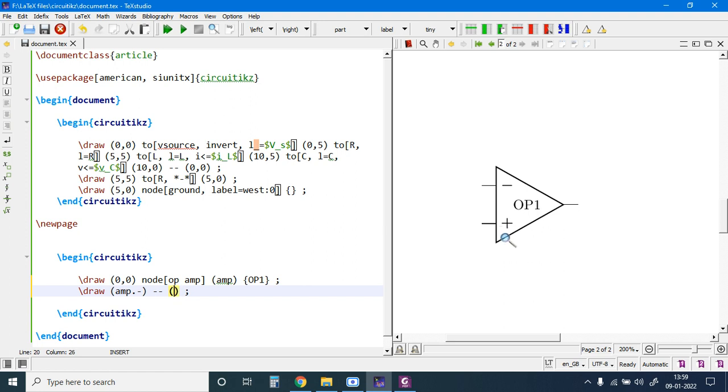Now another problem. The problem is I do not know the coordinate of this. So I do not know the coordinate of the point which is 1 point left to this point. Then how to get this point? Now comes the relative coordinate. Till now we have done everything in absolute coordinate in the previous example. Now we have to do in relative coordinate because we do not know the coordinates.